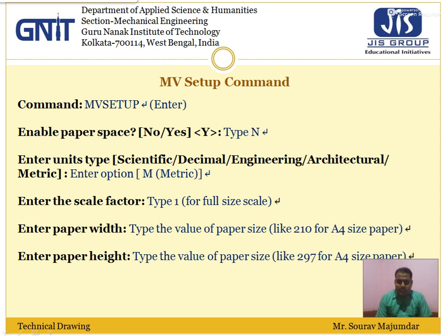We virtually create our drawing sheet, and within that drawing space we will draw all our drawings. So page setup means we virtually create our drawing space, nothing else. The command for this is known as the MVSETUP command.